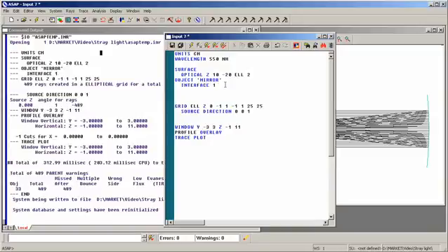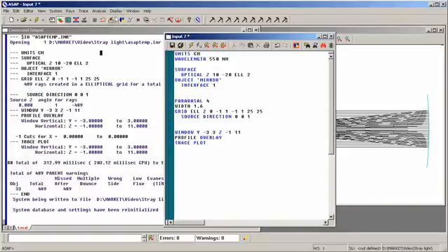We do this by telling ASAP that we want to include not only the base rays, which represent the geometrical information, but also the parabasal rays, which give us the wave optics information associated with the Gaussian beamlets. We say parabasal 4, which says give me 2 rays in the plane of incidence and 2 rays out of the plane of incidence. Width 1.6 represents the Gaussian overlap from one Gaussian to the other. All right, we're ready to go.